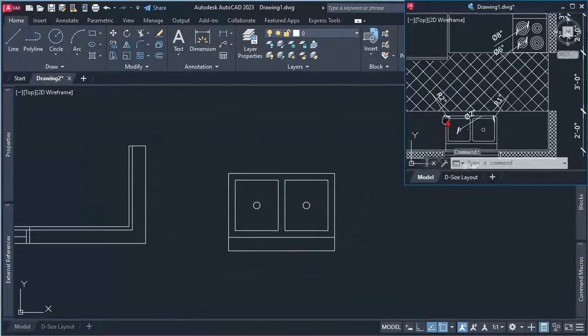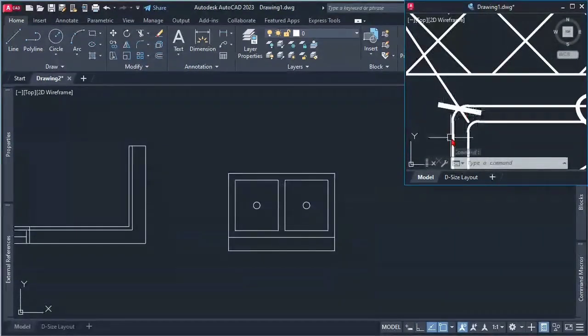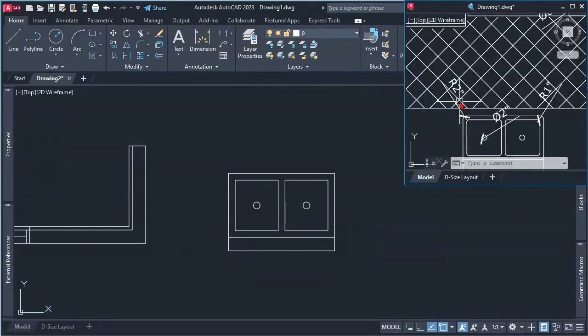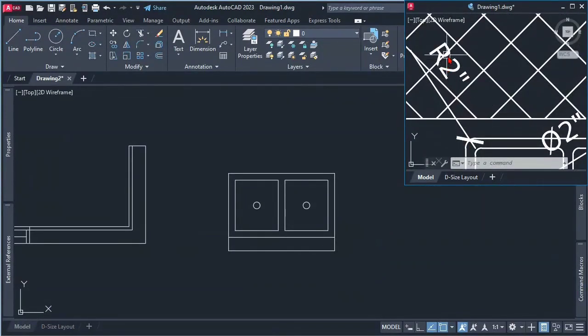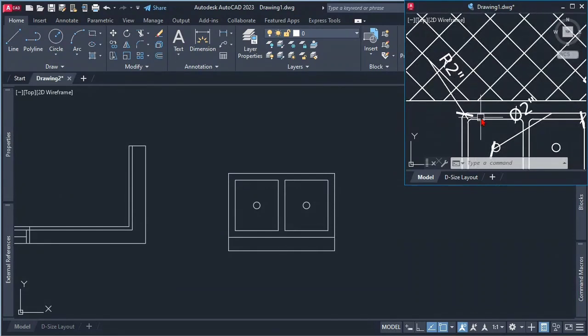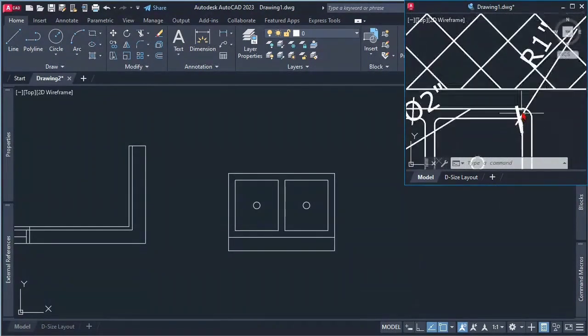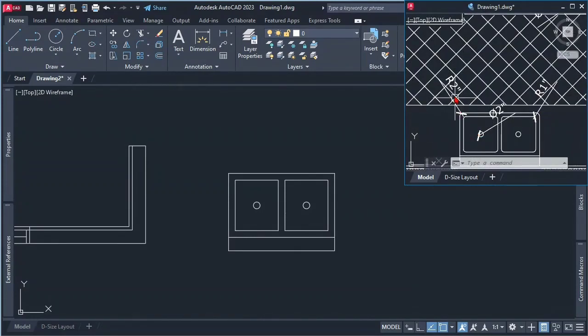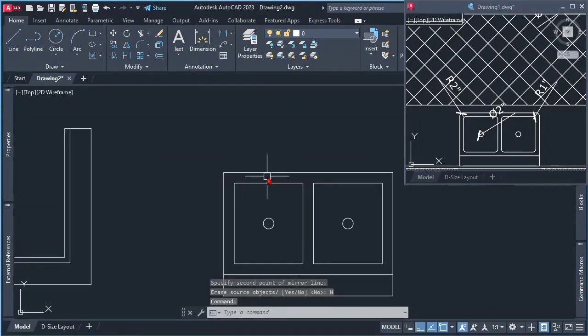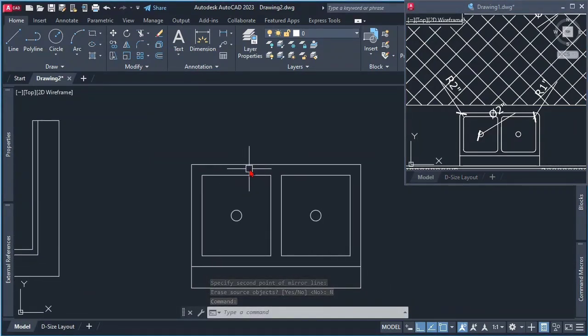Finally, the last step is to round these corners, right? So it's saying that this is rounded a distance of 2 inches, and this other one is rounded at 1 inch. Those corners are a radius of 1 inch and 2 inches. So how do we do that? We do it by giving you a new command. It's called fillet. So the fillet command, it's right here on the ribbon, but we could also use a keyboard shortcut F and press enter.